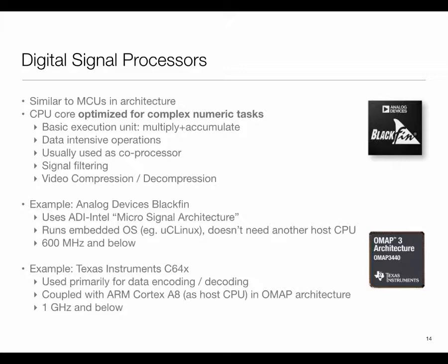So oftentimes you'll find that processors or so-called system on chips come with a tiny DSP on it. A good example is if you have an Android phone, you're likely using a Qualcomm Snapdragon chip, and it has a Hexagon DSP, which a few months ago they opened up for developers to use. Previously, it used to be hidden. The TI OMAP chip, same story, which is a chip used in BeagleBone, for example. So there are plenty of examples of a main processor, which may be a general processor like ARM, coupled with a DSP to go with it.